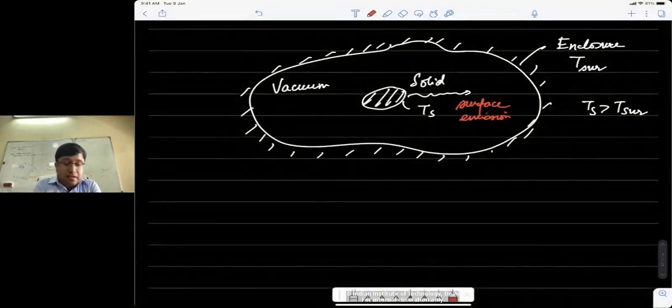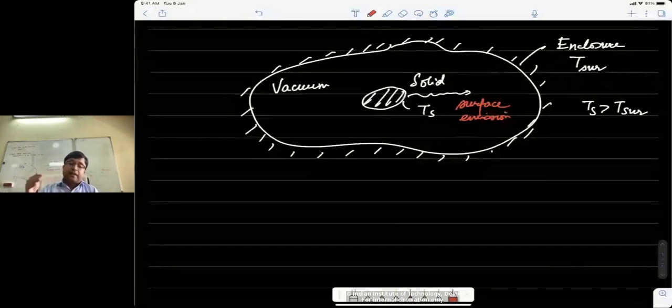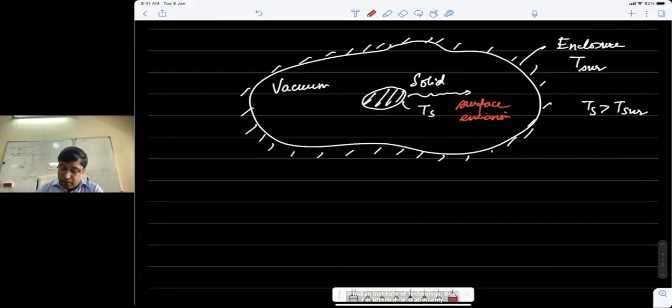But typically in solids, especially what I'm going to call opaque solids, we can consider the radiation to be a surface phenomenon. And what we can assume is that a thin layer at the surface, which is about a micron in thickness, is what really radiates energy outside. So you don't see radiation from internal matter reaching out. That gets absorbed internally only, but then it's the outer layer, which is roughly maybe 1 micron, but for practical purposes for us, it is basically the surface itself, which is going to be radiating. So we will consider radiation in this course to be a surface phenomenon.